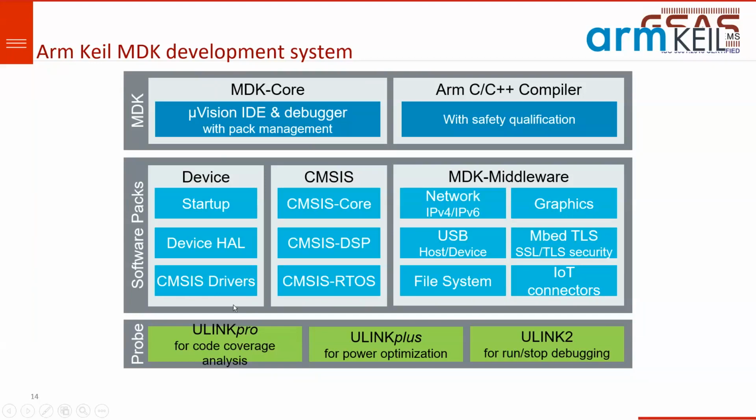Then we have software packs. This is called DFP, Device Family Pack. Device Family Pack, as the name suggests, supports the files associated with developing code or firmware for that particular device. The device is a microcontroller, an ARM microcontroller.